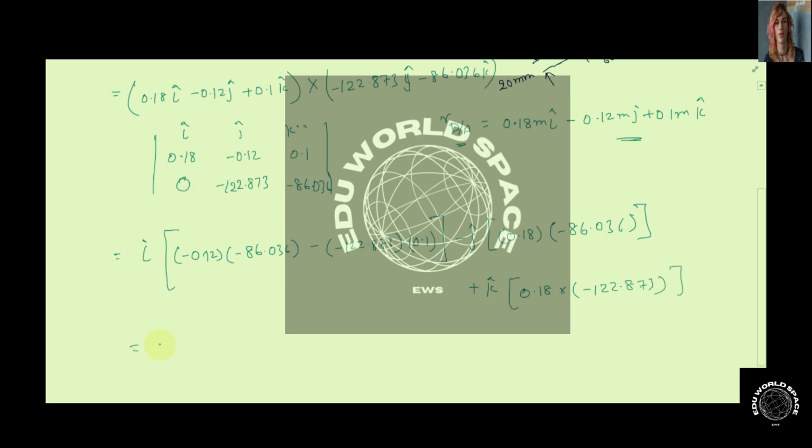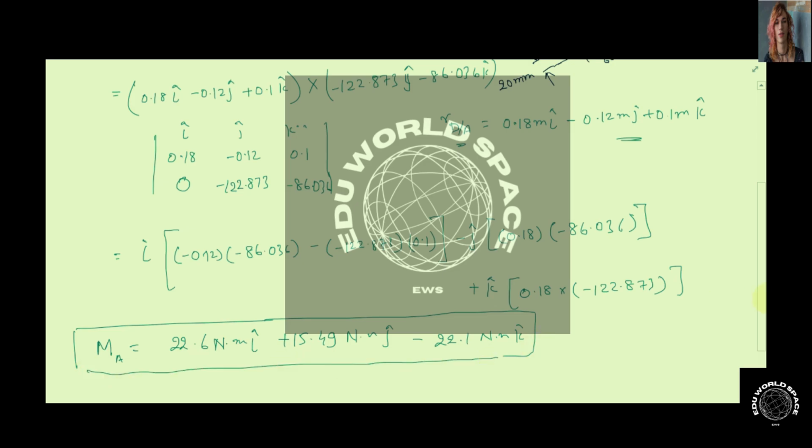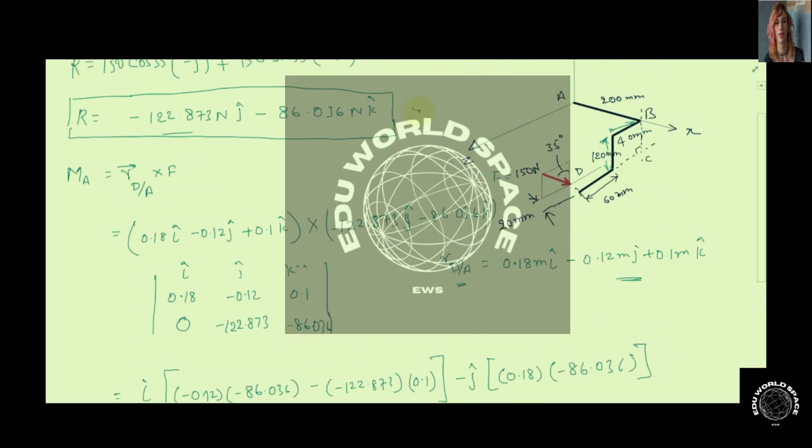So we can solve this. It comes out to be 22.6 Newton meter i cap plus 15.49 Newton meter j cap minus 22.1 Newton meter k cap. So this is the expression for the equivalent moment that is acting at point A. This is the answer for the equivalent moment, and this is the answer for the equivalent force.